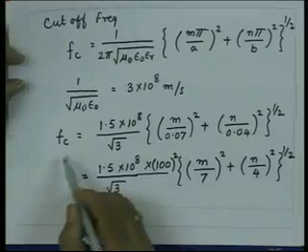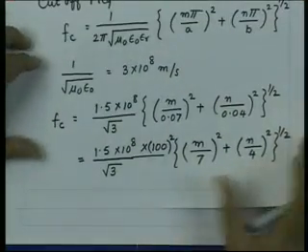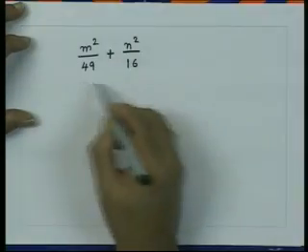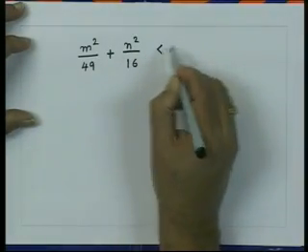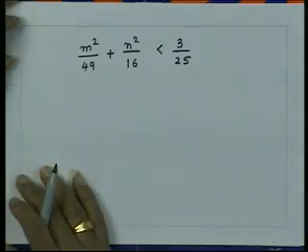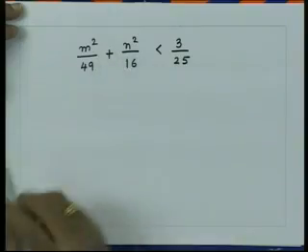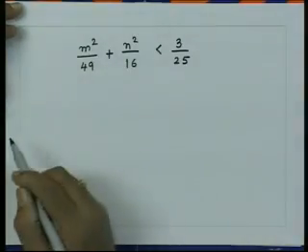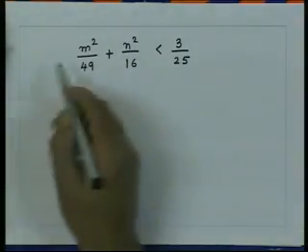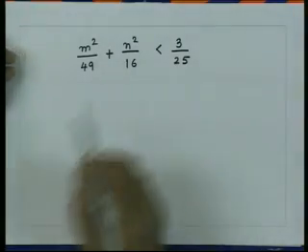So, what that means is, if I substitute here for the frequency, then if this quantity is less than 3 upon 25, then the modes will propagate. Now we can try different values of m and n, and as we know m and n both are integers. So, we can start with all possible combinations of m and n for which this condition is satisfied.